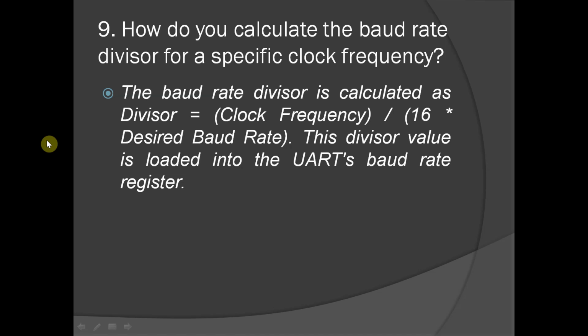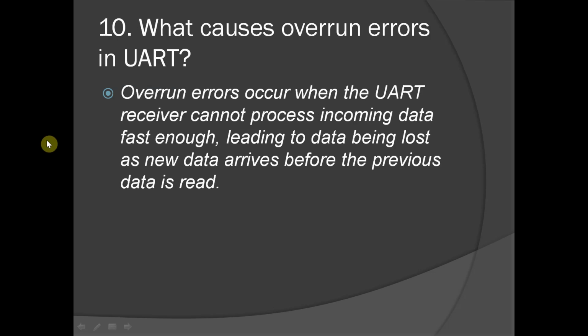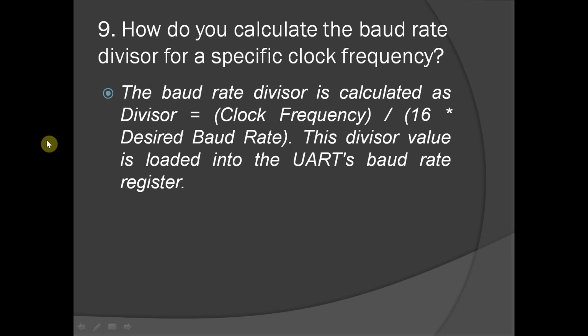So generally the receiver frequency must be greater than the transmitter frequency. Or else we will use async FIFO. But sir, if the transmitter is sending fast and the receiver is not receiving at that rate, there is a mismatch in baud rate, then there is a data loss, right? Yeah, that's why we are using async FIFO to store the missing data. Asynchronous FIFO, right? Yes, async FIFO.